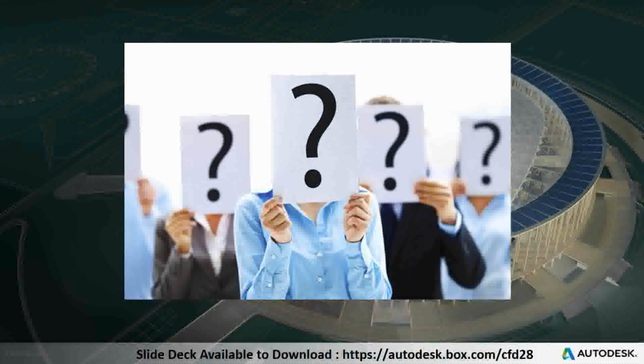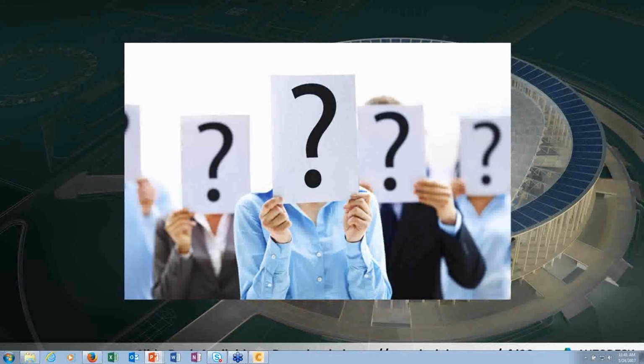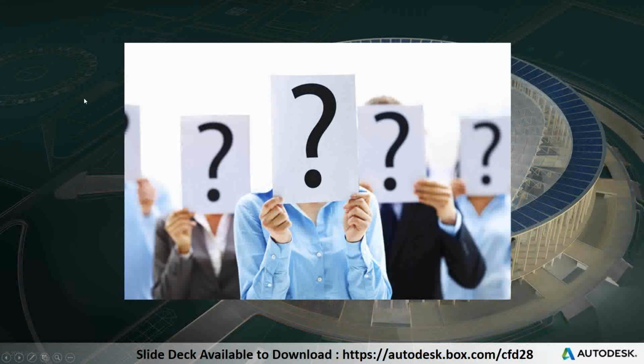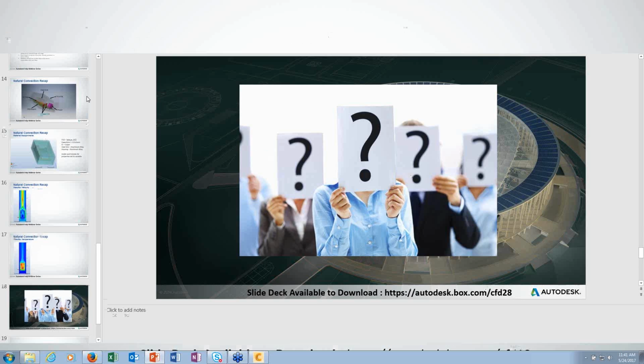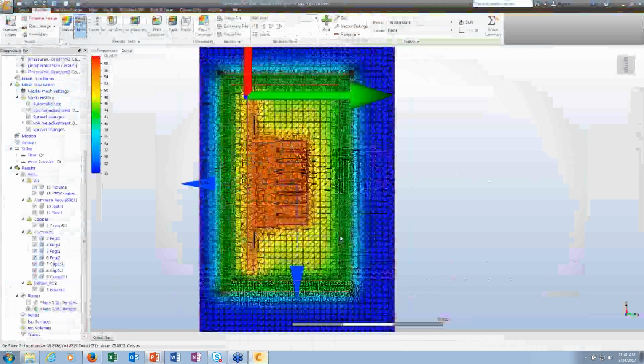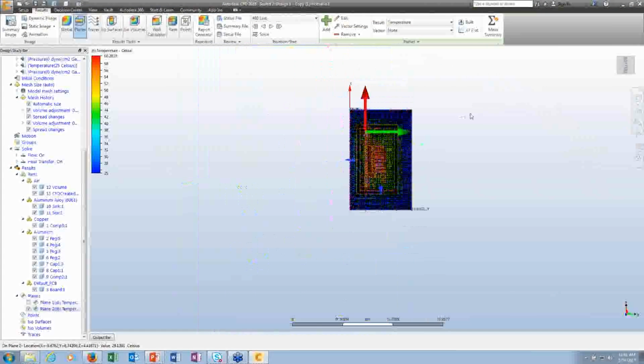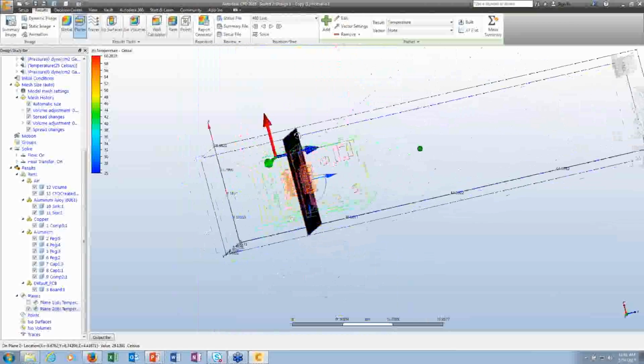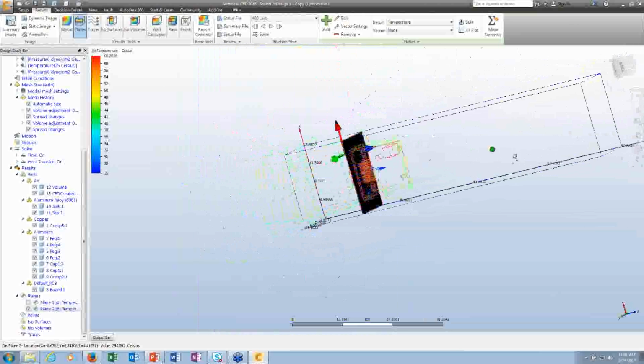Marwan, I'd like to touch on one last thing with the natural convection. I usually spend a lot of time looking for recirculation. Generally, it's going to be across the outlet, because your velocities are so low in natural convection, and by the time you're at the outlet, the temperature differences are pretty low. So generally, I drop a plane in there, across the outlet.